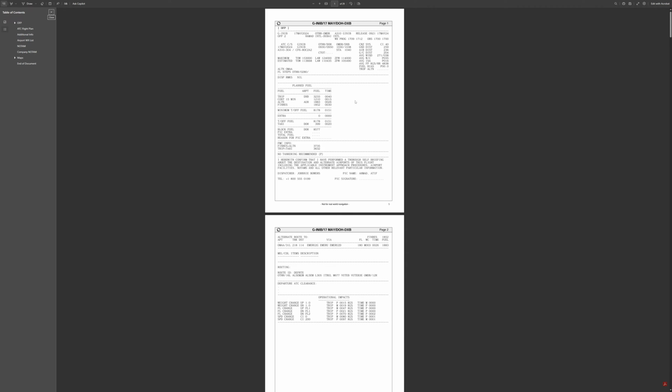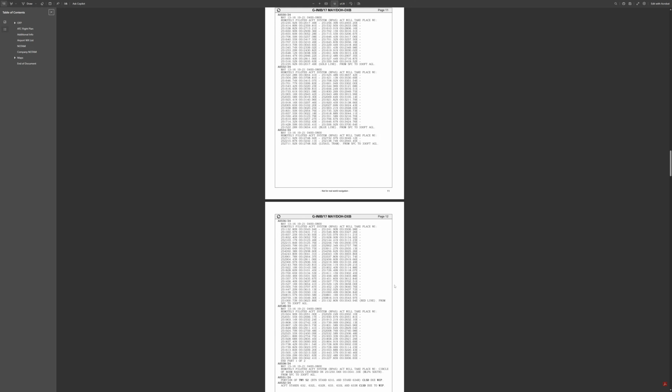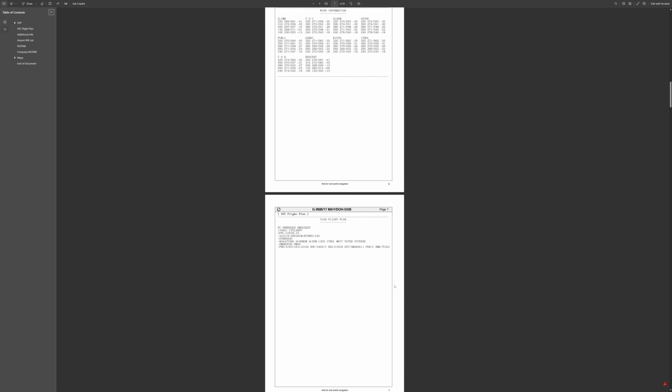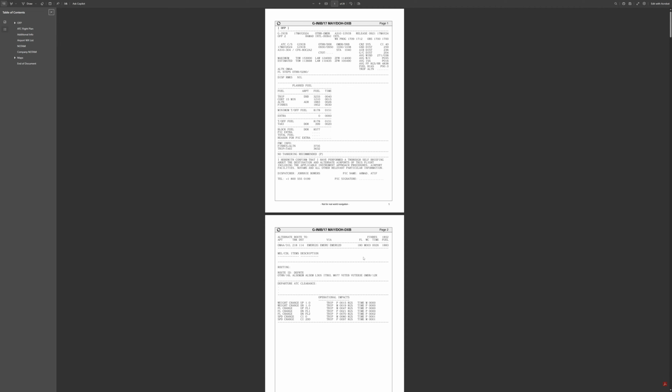And there is also a tutorial on the Simbrief site where you can just go and watch that tutorial, and it will tell you different parts of the operational flight plan and how to read it. So it's got all the information related to the arrival procedures, the departure procedures, the weather, and the wind information. So in this video, I will also tell you how to read it. So first of all, there are a few things that we have to take into consideration, which are the fuel and the zero fuel weight. So we have to enter this information over there in the plane.